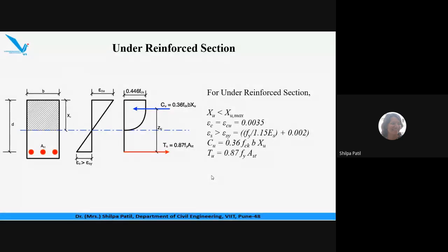Ultimately, what you said, that the amount of steel provided is less than the amount of concrete, is not the truth. Actually, the percentage of steel is less than the critical percentage steel, and because of that, the steel reached its maximum strain value first rather than concrete. We cannot compare the quantity of concrete with the quantity of steel. Keep this always in mind. We never say that concrete is more than steel or steel is more than concrete. Is it clear? Yes, ma'am. Okay.